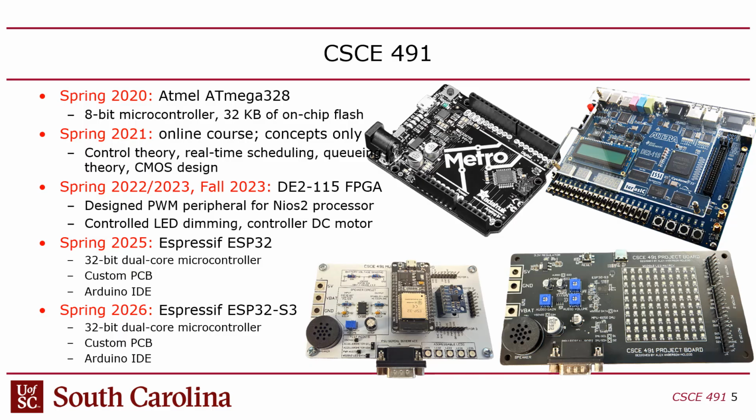And the other main beef I had about this board was we were using the original ESP32, which didn't have debugging capability. There was no way to debug your code, aside from doing the ridiculous print debugging, which is, in my opinion, terrible. I hate that, right? There was no way to actually stop your code in a debugging environment and inspect memory and variables, right?